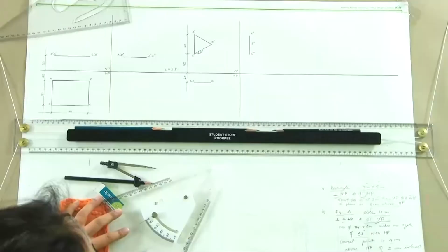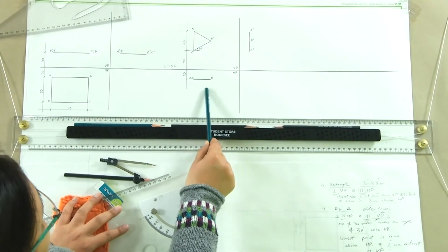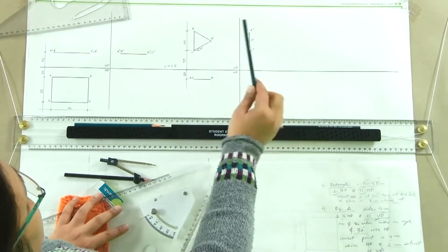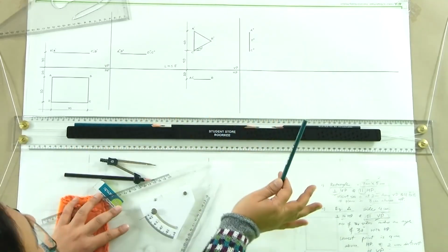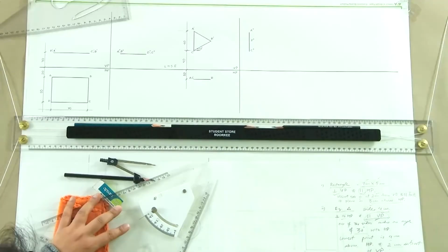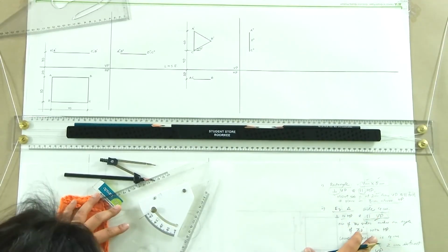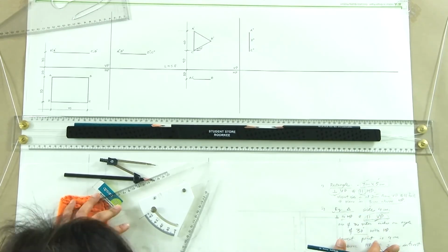Please remember that we will only dimension where the true dimensions or true angles or shapes are being seen. We will never write any dimension here. What this distance is, is none of our concern, though this side is also 40, but we are not going to dimension it, we are not going to write it. So, this is how we draw the projections of this equilateral triangle, which is parallel to VP and perpendicular to HP, and with these given dimensions and conditions.